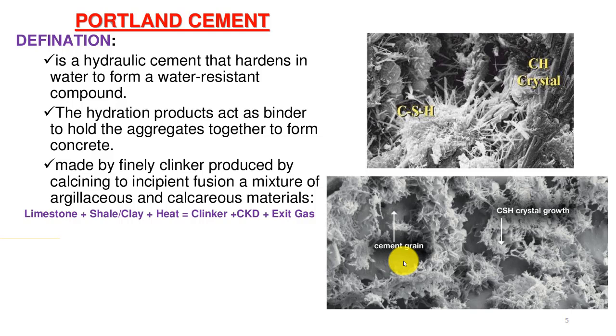If you grind cement in a very minute particle size, lesser than let's say 10 micron, it would have a higher rate of hydration, because the more the surface area you have, more would be the reaction, more would be the vulnerability to get reacted. So the cement particles only hydrate up to 20%.